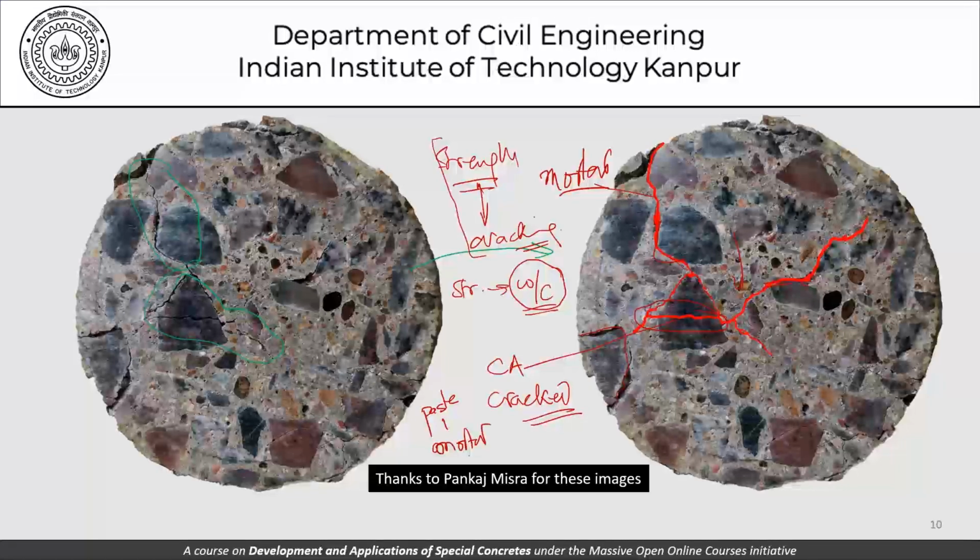So that really is an important issue, and you see the cracks are going through this. The fact that the aggregates normally do not crack and cracks go around the aggregates happens because of the type of aggregates that you use. I'm not going to talk about it more than that. Only later we'll talk about it. Just think about this issue and we'll come back to it later.